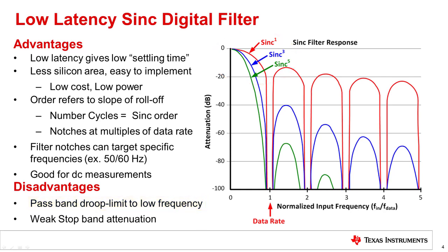Normally, for any AC signal, the ideal filter has minimal attenuation and a flat response in the passband, but this filter's response clearly is not flat. Thus, this type of filter is limited to DC and low frequency signals only. Typical conversion rates for this kind of filter can be in the low hertz up to a few kilohertz.